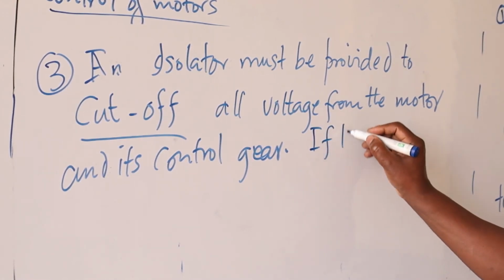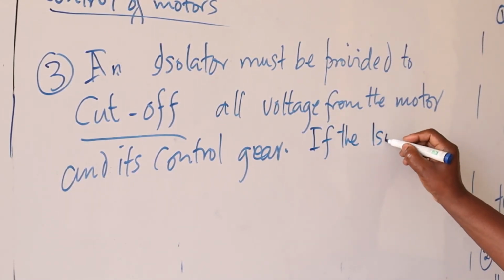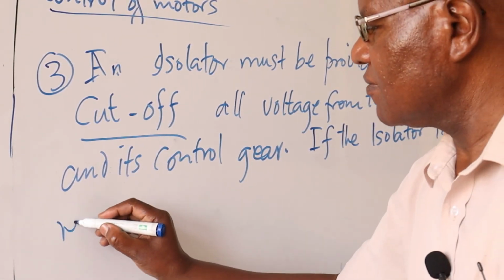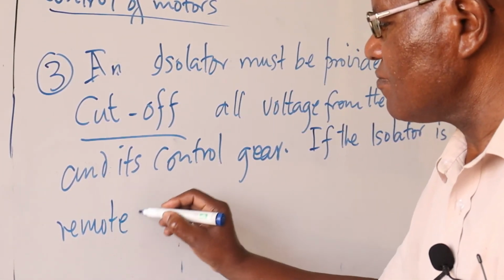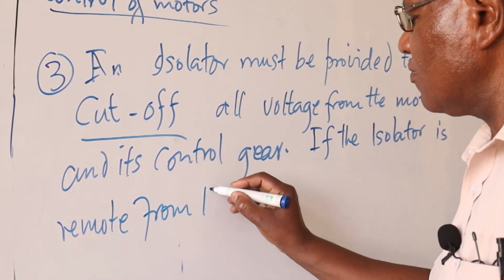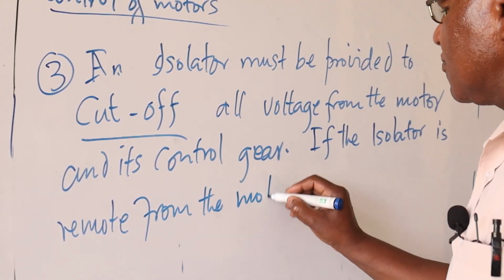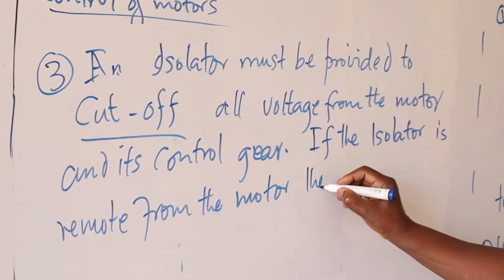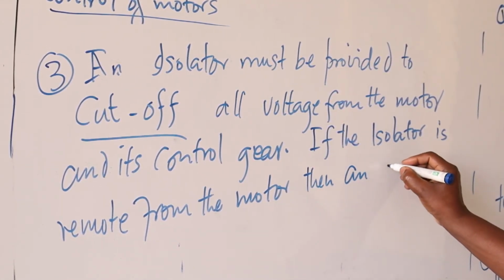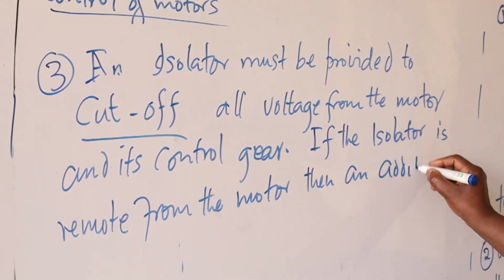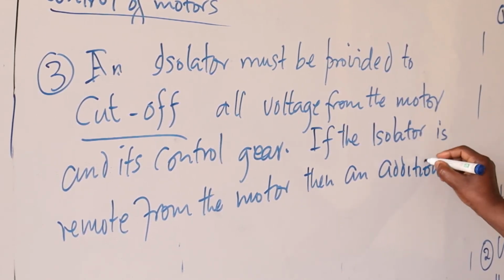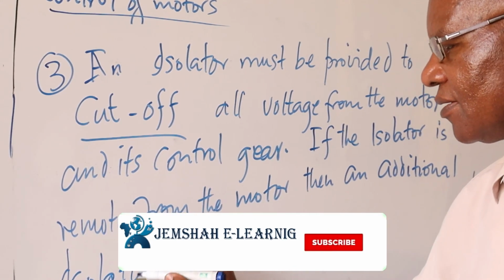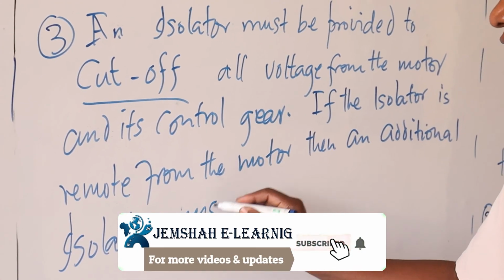And if the isolator is remote from the motor, then an additional isolator must be provided.